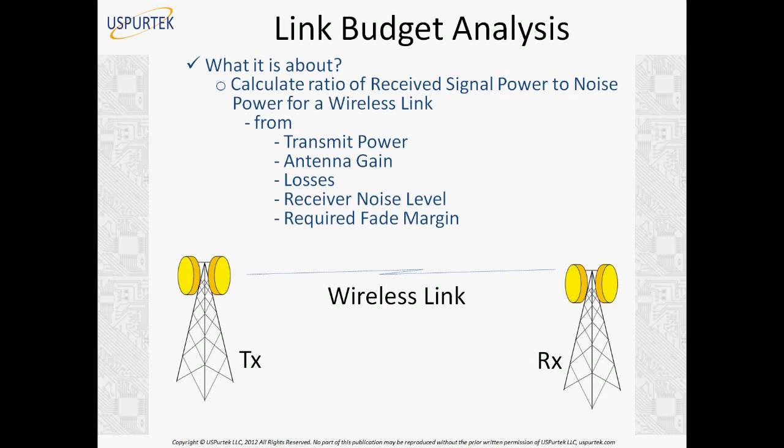We need to know the transmit power, the antenna gain on both sides, transmit as well as receive, all the losses in between the transmit and receive antenna, and the receiver noise level. Any receiver will pick up not only signal but also noise that is present all around us.